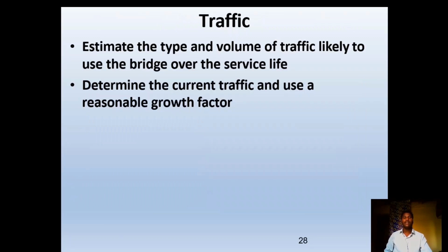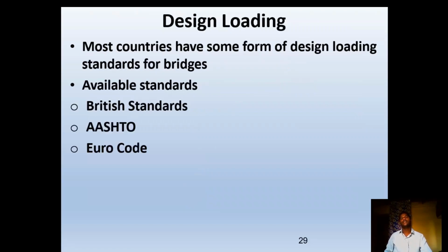Traffic. Estimate the type and volume of traffic likely to use the bridge over the service life. Determine the current traffic and use a reasonable growth factor. Design loading. Most countries have some form of design loading standards for bridges. Available standards are British standards, AASHTO and Eurocode.